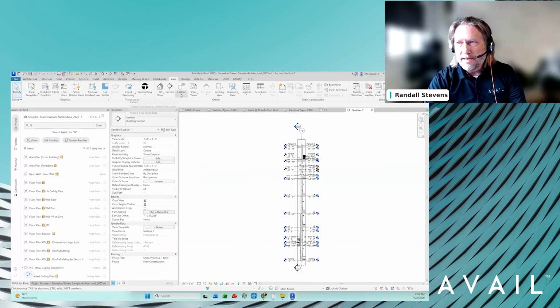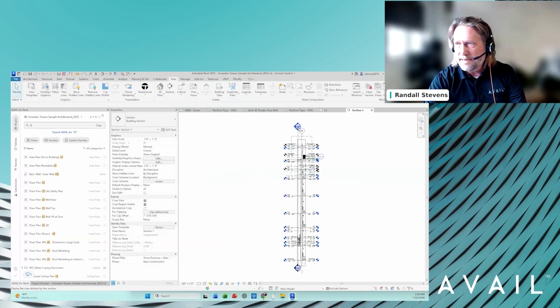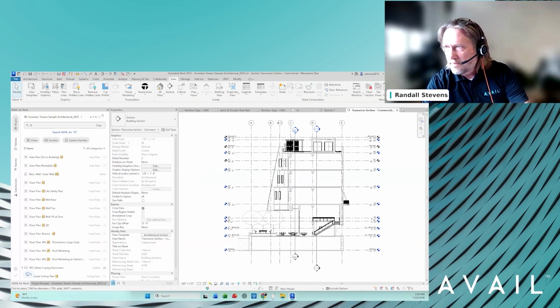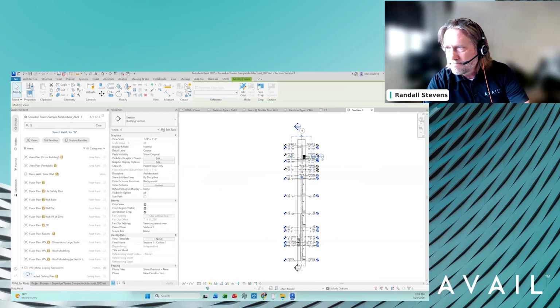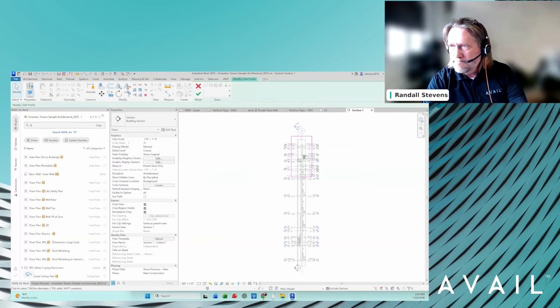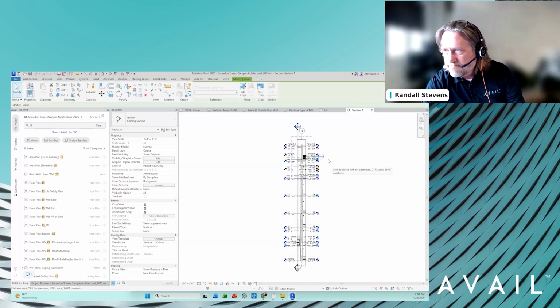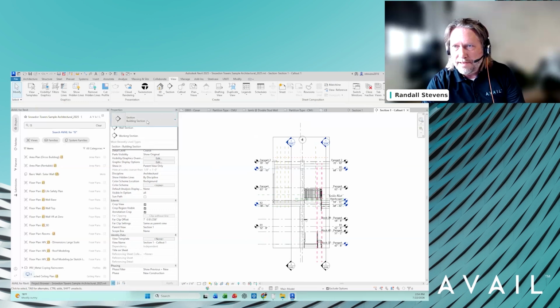All right, so now let's do a call out. So I'm just going to do a quick call out of this guy. And I'm going to convert this into a detail view. So my view scale, I'll show you as this data is coming in.